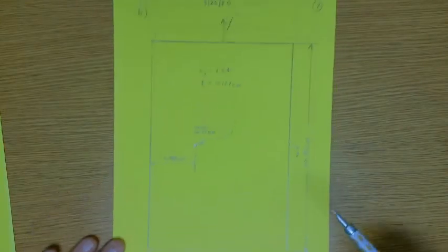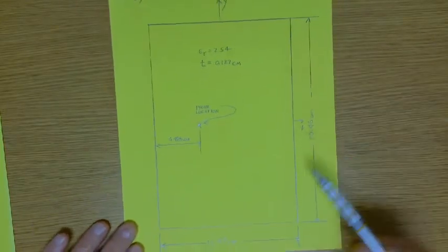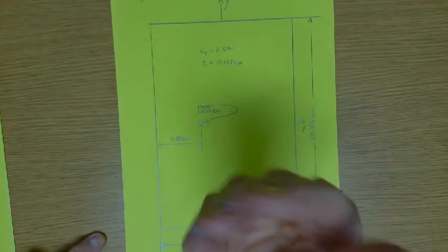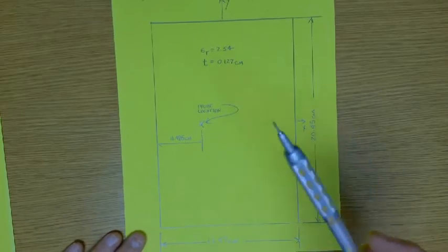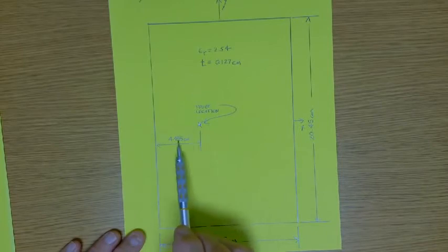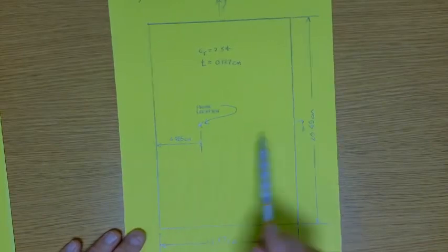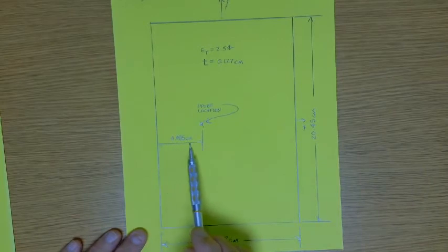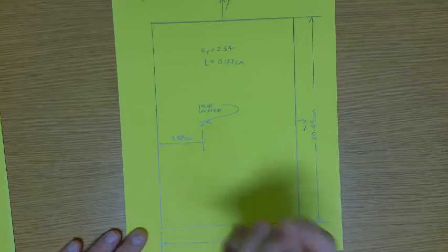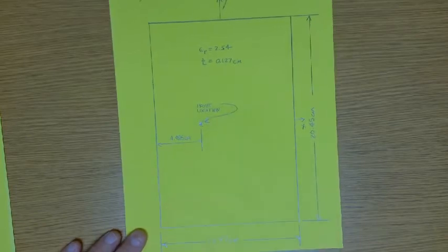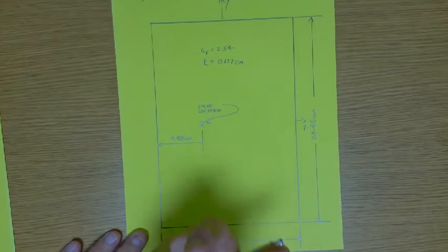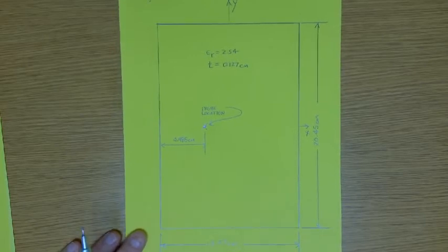20.45 centimeters this way. So this is looking down from above, X, Y, radiation up, right, toward the camera lens. Here's the feed location in the center of the patch. Here's the center line. And we moved it 4.485 centimeters over. And so this is where the center conductor of the coax comes up. And so that's a blob of solder. Okay, so we're feeding it here. And then the input impedance that the 50 ohm coax sees is 50 ohms. So it's matched at 660 megahertz.